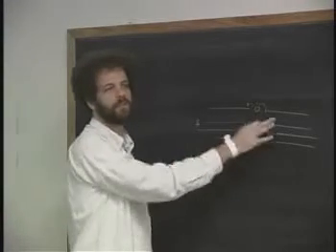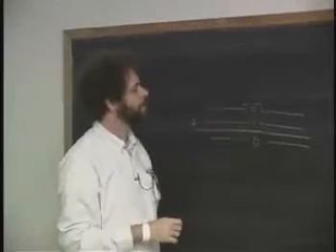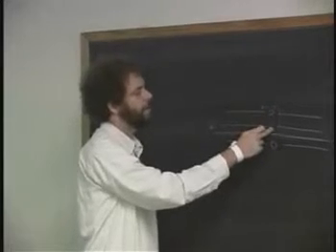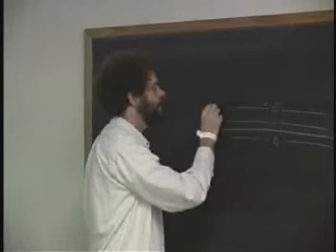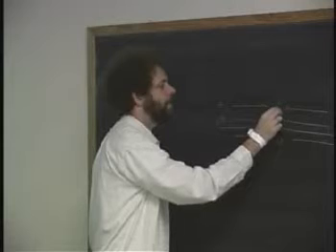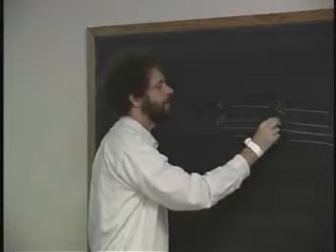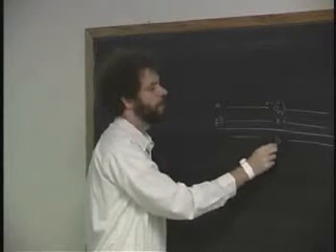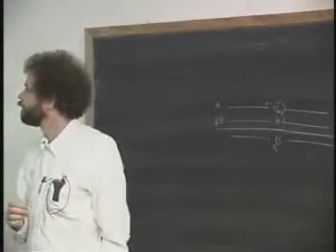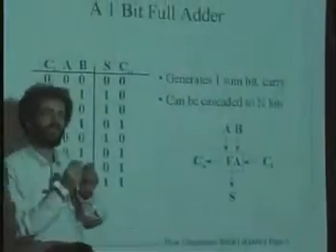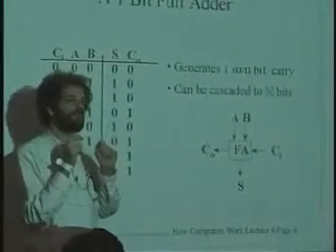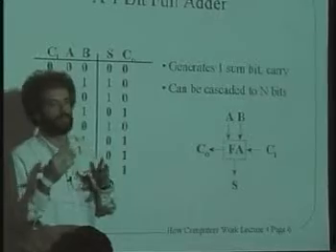So this is nothing more than the binary version of adding numbers that you've known how to do since grade school. So there's the idea of I need to sum together A and B sub I, because here's A and here's B. So this is A sub I, the bit I of A, and here's B sub I. But I also have a carry in and a carry out as well as sum sub I that comes out of here. Okay, so there it is. A single bit slice of an adder like this, and for now I'm going to concentrate on just adding, because it turns out that of all the ALU functions that we're going to do, add is sort of the most difficult of them. And, or, stuff like that are actually pretty easy.